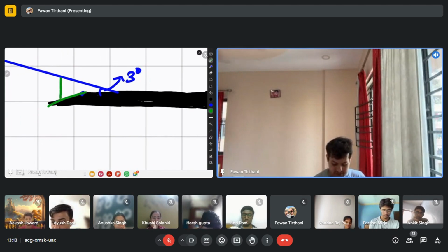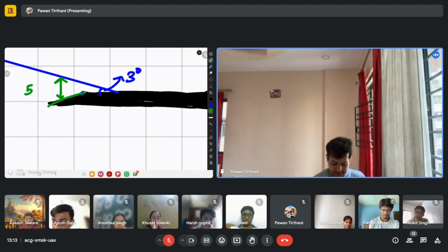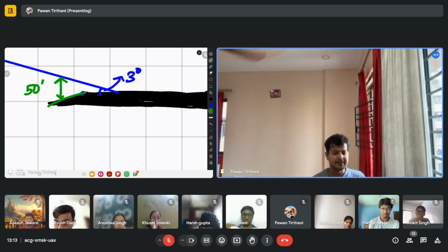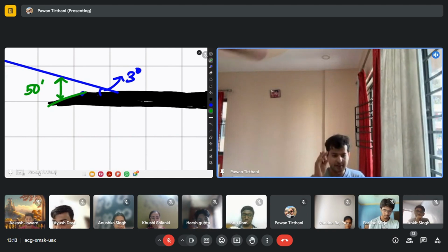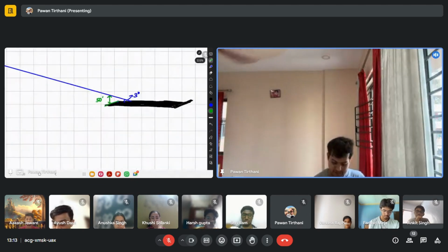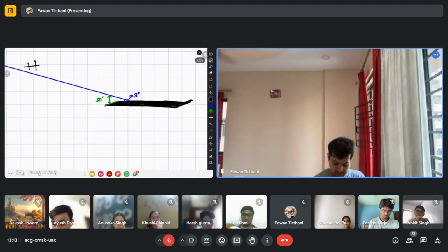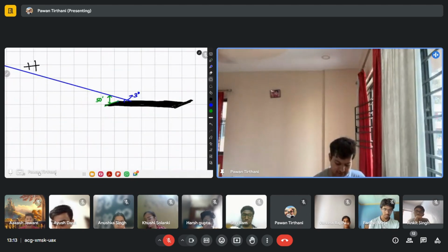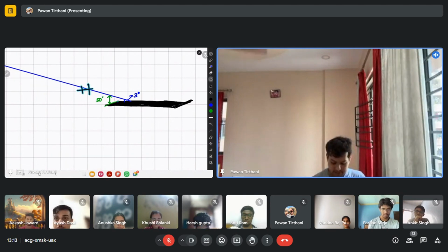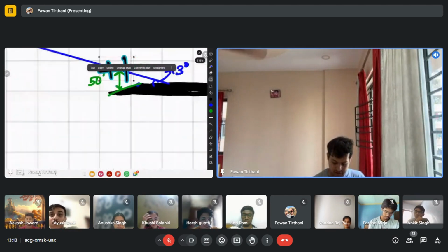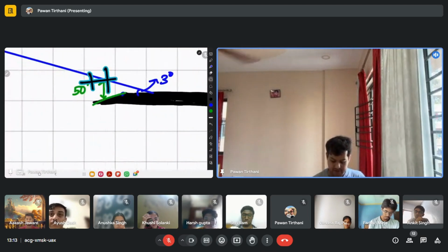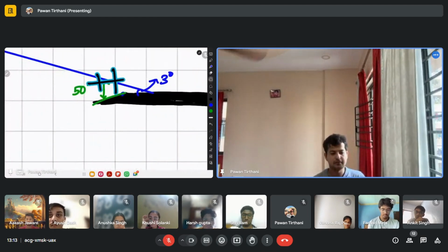This crosses the threshold at a height of 50 feet by default. Every time you come in for a landing throughout your entire life, everyone remember this. Whenever you come in for a landing, you are supposed to be over the threshold at 50 feet.